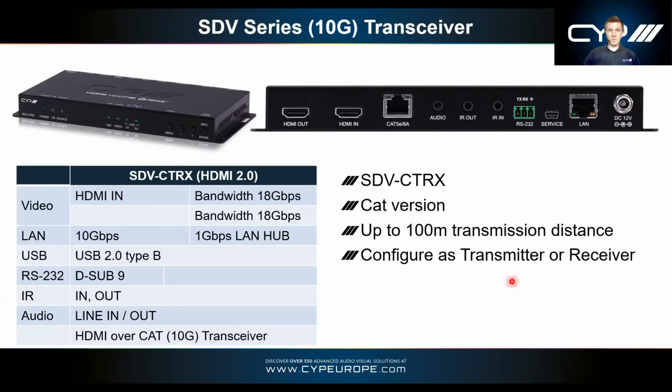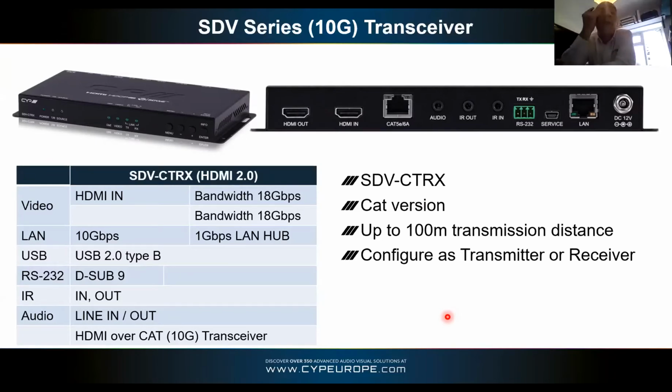And the audio as well. Do you want to cover that while you're there? The audio connection on the back there. Yeah, so with SDVoE, when you're on the transmitter side, the audio jack isn't labeled as in or out. That's because in the SDVoE system, when you're with a transceiver in transmitter mode, you can decide whether that audio is an input or an output.